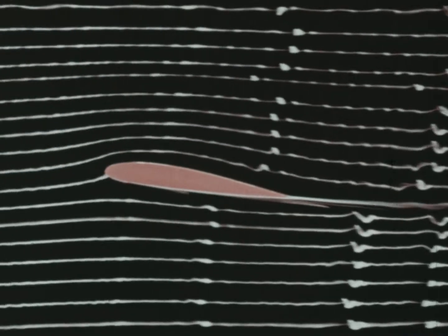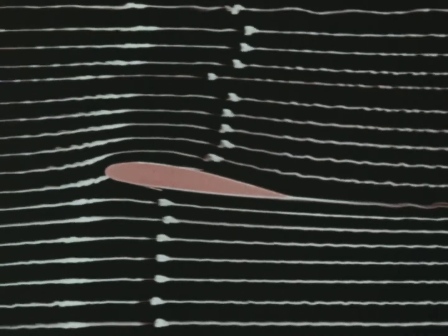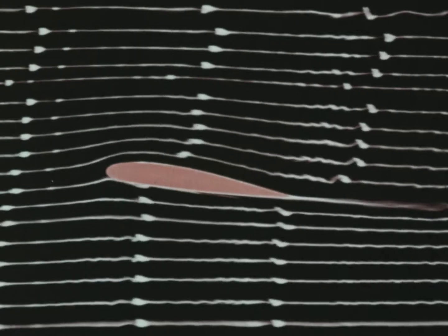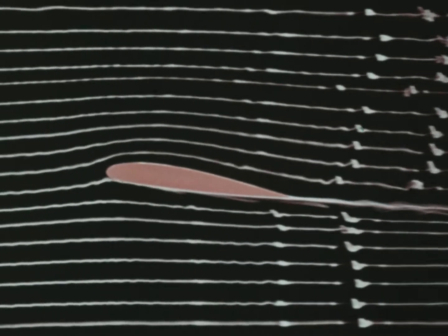For when a fluid in motion increases its velocity, its static pressure, which acts at right angles to the direction of flow, decreases. And when the velocity is reduced, its static pressure increases, so that its total sum of energy always remains the same.